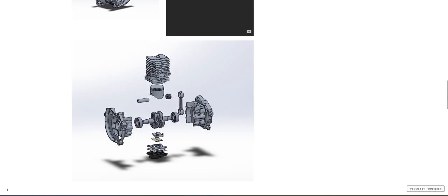For the flange part, once again, it can be made by sand casting for the cast iron, then machined, or we can make it out of aluminium with sand casting or die casting. So I'll just give you different technologies for that. For the rod and for the crankshaft, they must be made of steel, because you're going to get high impact and it's impossible to actually use aluminium for this. Any 3D printing possibility to be used here? The answer is no.